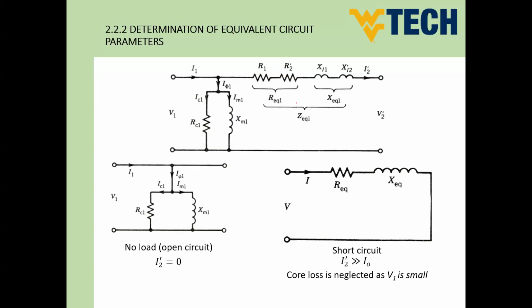Also, in order to know, for instance, the voltage regulation, which depends on the difference between the input and output voltage of the transformer, we have to know all the parameters of the transformer. So generally, guys, in order to make any kind of evaluation for a device, you have to have the parameters. For that, parameters identification is very important.